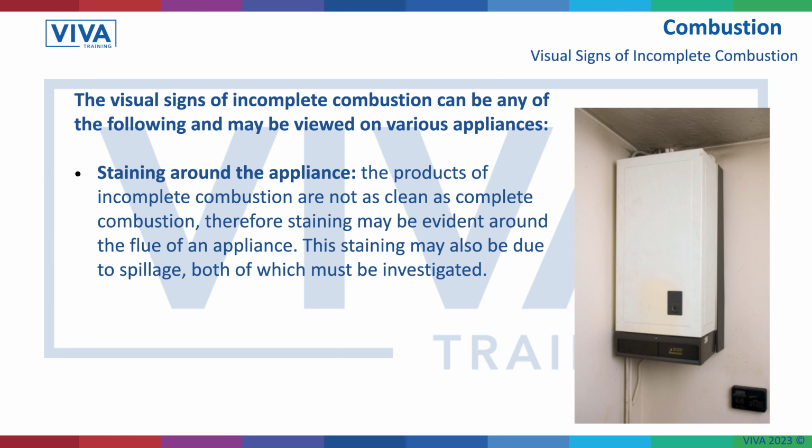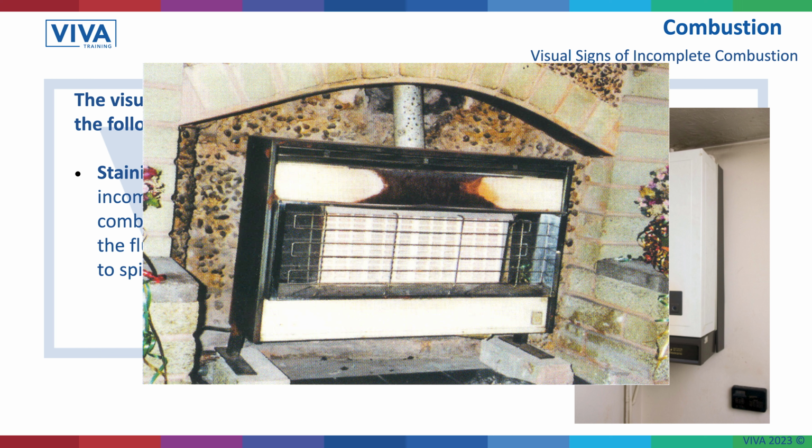If we look at that gas fire, that's a real bad example of a gas fire that's not been serviced properly. We can see it's scorched on the front canopy. That's the bit of the front. We can see where the paint's worn off. It's really in bad condition. If I saw that, the first thing I'd be doing is saying to the customer, look, you can't use that appliance. I'm going to condemn it. I'm cutting that off.